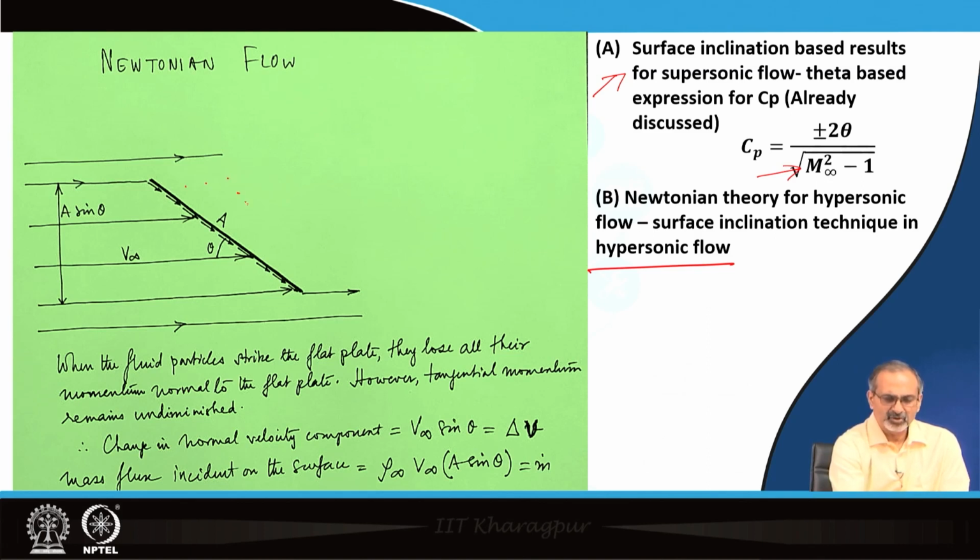Behind the surface not much happens, because due to the rectilinear propagation of the fluid elements there is no flow turning which can happen, and based on this theory, when low speed flows were tackled there were severe anomalies. However, in this era where hypersonic flows are increasingly studied, it was found surprisingly that the Newtonian flow model fits so well into this framework.